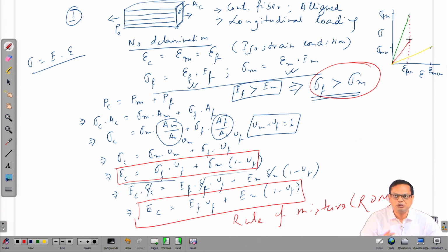Okay. So, then at that particular load, obviously, if the fiber has failed, the matrix will not be able to withstand that high amount of load. So, there will be instantaneous matrix failure. Okay. Now, the point here is what we want to understand. So, basically, this is sigma composite, and epsilon Fu is equal to epsilon Cu as well. I hope you understand this point.